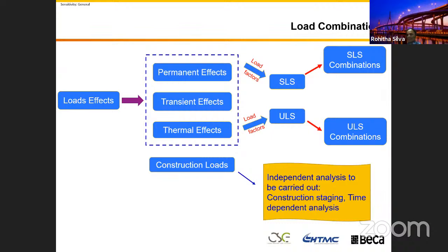I put this one in big. If it is construction loads, the way we construct differs from bridge to bridge. We have to do a special analysis for each particular bridge, so you can't apply the same standard; that is beyond the standard. You need to do the analysis, especially if in the construction stage analysis the creep and shrinkage effect significantly impacts the bridge behavior and the forces. We need to calculate them.